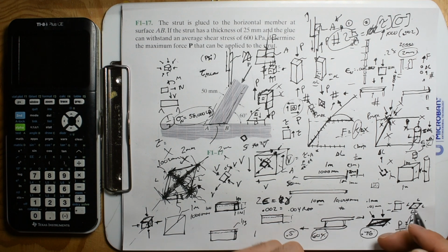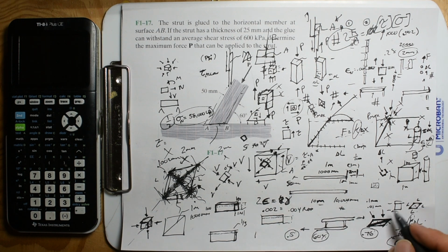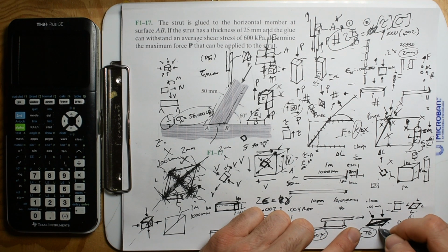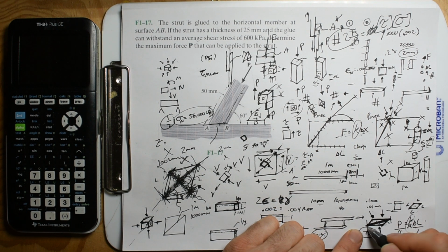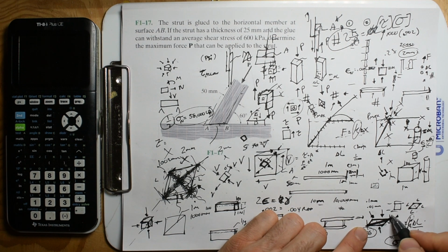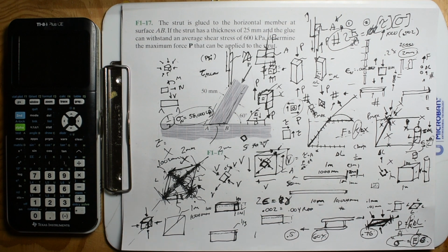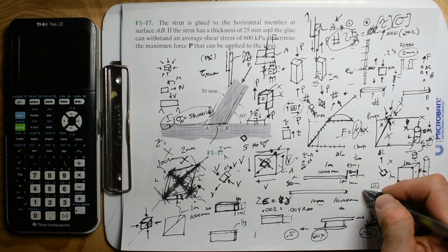So on that plane, it's no different than that being an axial tension. And worse, it's being compressed in at the same amount, and we talked about how Poisson's ratio reduces the amount that you can actually change this length, because it already squashed out a bit. So yeah, from my perspective, there's some empiricism in the use of the term.